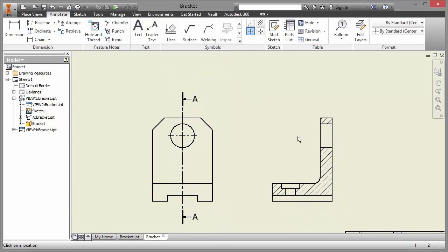What we've got now on the side view is that we know that these two are the side view of these holes here, but we're just going to tell the end user that they are definitely round. So I'm just going to click on these center points to create a center line.